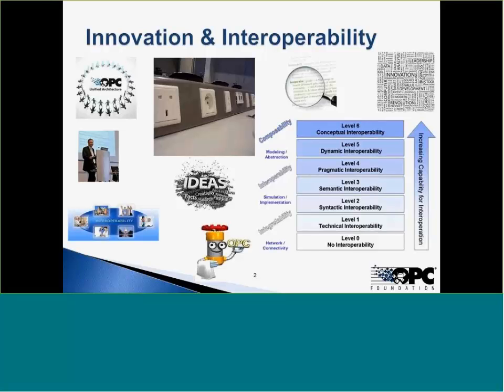was about the Microsoft technology, and as Scott attested to and told you what a client and server was, it's essentially like a translator where the server knows how to talk to the underlying devices, and then it communicates via OPC to the client application, translating the information into a standard representation.